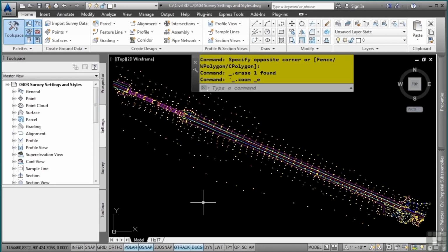As with everything in Civil 3D, styles need to be developed and settings need to be defined for all survey-related data. Styles include point, figure, network, and description key sets, which map raw survey descriptions to the appropriate point styles, label styles, and many other point-specific parameters. And the Settings tab is where you need to do some of the setup related to the survey functionality.